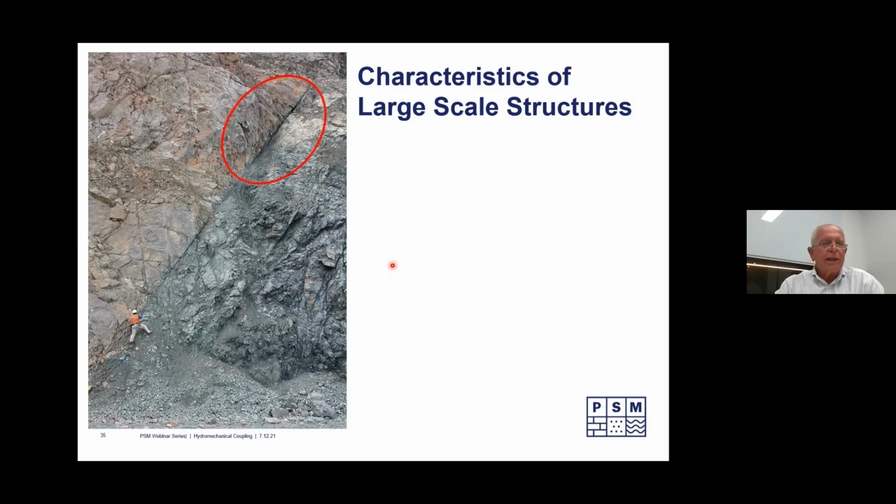If you look closely, you'll see the aperture along that structure there. The structure itself looks pretty poor, very ground up. But there's still aperture. There's still a crack. And if you look at how wide those dark lines are, just compare it to the helmet he's wearing. Those apertures are probably 50 millimetres, at least. They're substantial.